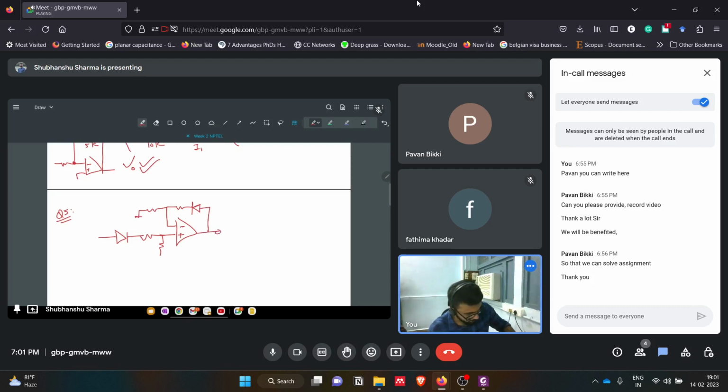Whenever you get a circuit, analyze why those op amps are there and in what configuration they are. Are they in inverting configuration? Non-inverting? Are they acting as a differential amplifier, a summer amplifier, differentiator, or integrator? That's why these topics are taught separately, so that when a complex circuit comes, you can use all those concepts, bifurcate a particular question into pieces and then solve it. Then it will become easy for you.